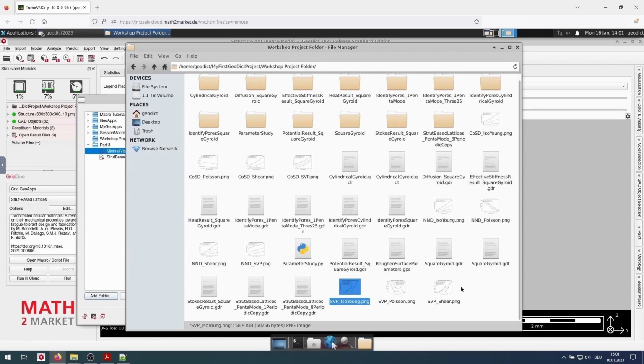So this gives us a rough idea that the near node diameter and the center of strut diameter, if both are increasing, so does the solid volume percentage, and if the solid volume percentage increases, also the Young's modulus increases. But it seems that the near node diameter has a larger influence on the Young's modulus compared to the center of strut diameter. Now, with the parameter study finished,